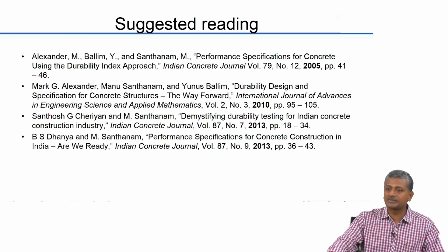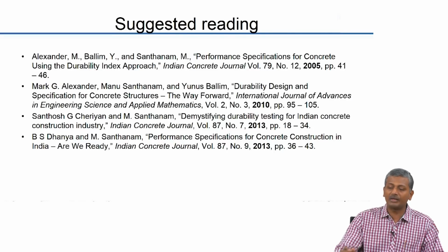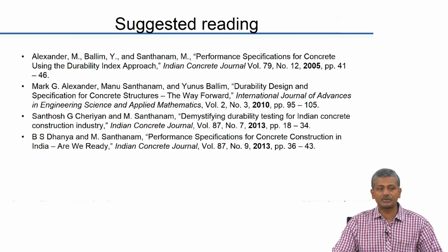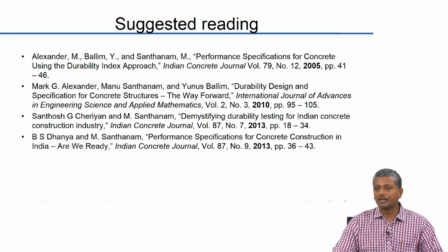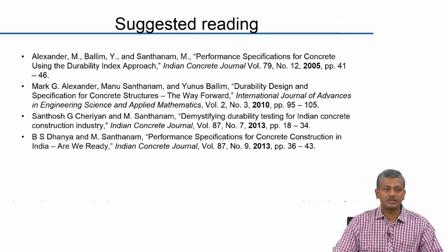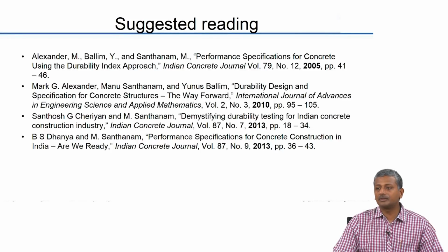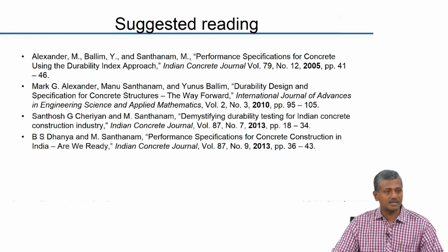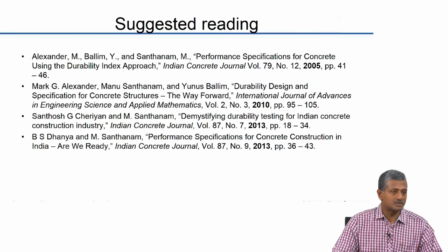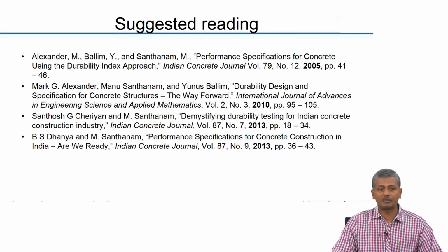There are a lot of papers in this subject. I have only selected a few where we have directly provided our inputs also. So, there is a lot of research on this has happened in our laboratory, primarily with the research project that we were involved in with Lafarge, which is one of the largest construction material manufacturing companies. And we did this research over a period of 4 to 5 years, and we produced a lot of data based on this research, which talks about how these tests can be utilized and what we can do with the values we get, the kind of durability parameters that we obtain from these tests. What do they signify for the performance of the concrete?